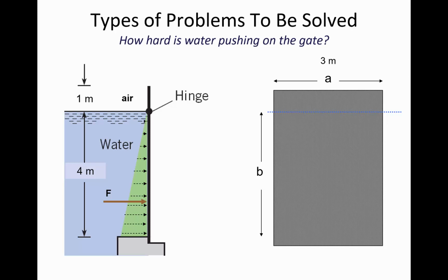It's the hydrostatic force. And in reality, there's not just one single point force that's acting on the gate. But if you integrate the distribution of pressure over the area, then the effect of that integration is the same as a single point force located at this depth.